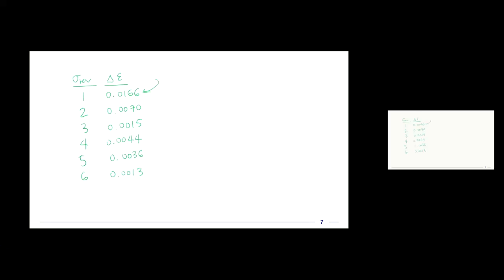Okay, so how do we go about finding our cycles to failure? That's what we need next. If we know how many cycles to failure, we have one of these cycles in each block, so then we can sum that up and see what our cumulative damage is for that block.